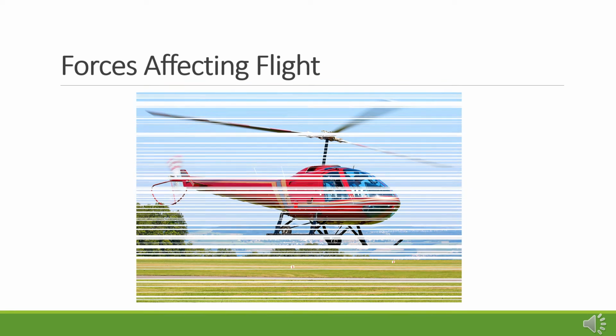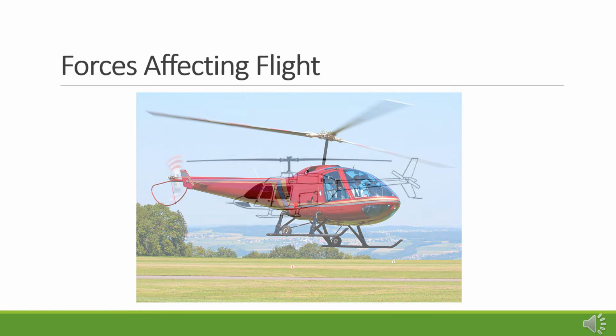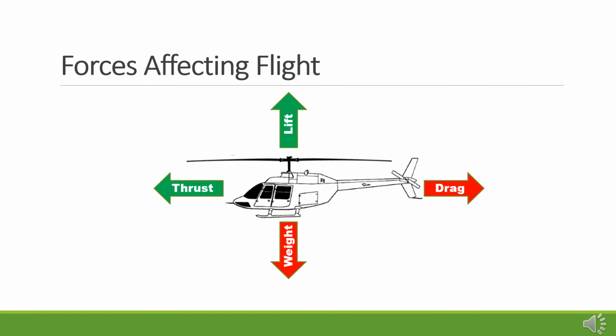A helicopter is classified as a rotary wing aircraft. In other words, a helicopter does have wings, but the wings rotate around a central hub or hubs. A helicopter's main rotor or rotor system is the combination of several rotary wings or rotor blades and a control system that generates the aerodynamic lift force that supports the weight of the helicopter and the thrust that counteracts aerodynamic drag in forward flight. The main difference between a helicopter and a fixed-wing aircraft is the fact that both the lifting force and the thrust or horizontal force in a helicopter are generated by the same rotating blades.